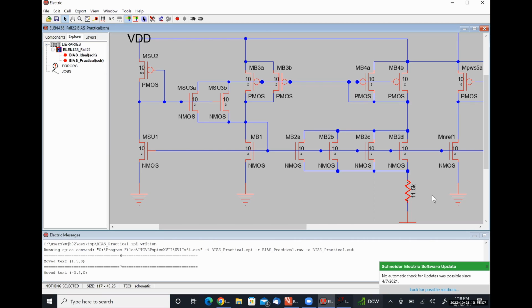What's the transient command? Dot tran, however long you want it to run as a DC circuit. That's all I need on that line. Yeah, dot tran and then some time duration. I know it's going to be plenty of time. Sure. Okay. It's DC. And then dot include and then the file path to C5. I thought you said 20 microamps. Right, okay. So I just need to go label the rest. Yeah, go label the rest and then you can start working on the rest of the circuit.